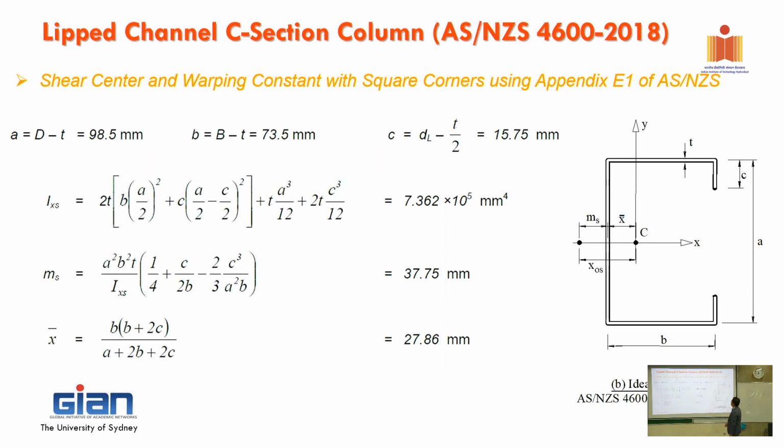So with that one, we can calculate IX, and then we calculate MS, then we can calculate the distance from centroid to the shear center. All right, that's very simple, straightforward, but a lot of equations, but it's very straightforward. You just follow that, and then you can work it out.